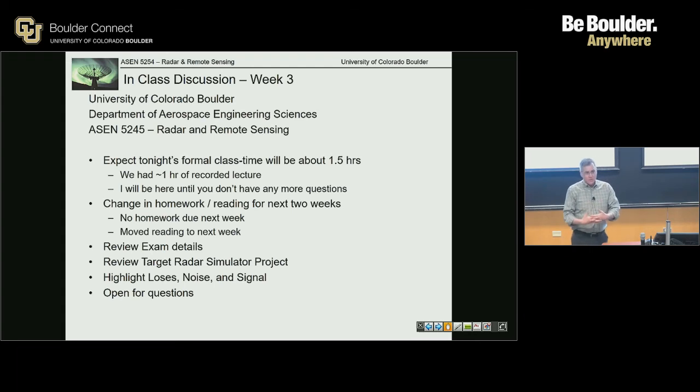Okay. But what a real radar does is it transmits a pulse, and then for every A to D, it makes a sample. Part of what we talked about in the lectures was that it's going to measure a noise number, and then added to that will be a target power. Some gates will have power from a target, others will not. And so it collects, in our case, 240 range gate samples. It would grab 240 samples and put them to memory.